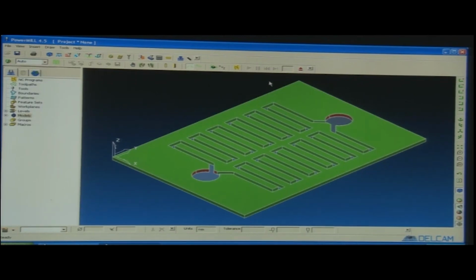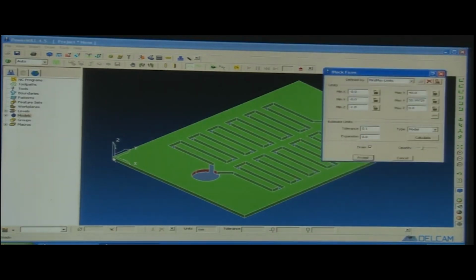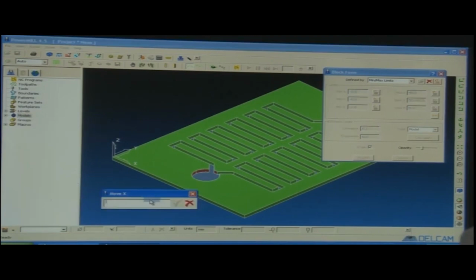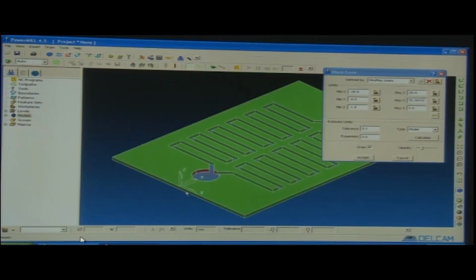Okay, now what if I need to bring it to the center of the workpiece? To bring it to the center of the workpiece, I can take the average of the values. Anyway, we could have taken any of the corners as the reference, but just to pick the center of the job as the reference, we can move x again, moving x to minus 20, because the total width for x is 40, so 20 would bring you to the center of the x dimension of the workpiece. So, it is in x center.